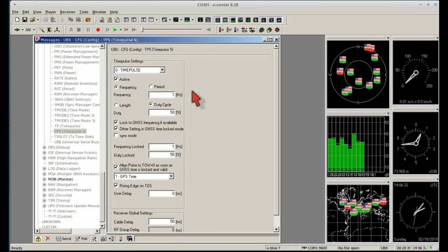There are now just the two frequency input fields of interest. The top is only used when there are not enough satellites, and the lower one is only used when there are enough. So, assuming the GPS receives properly, all your changes should only be in the lower field. If the GPS loses lock, that is the number of satellites is too low, the PPS switches to whatever you input in the upper field and ignores the lower one.